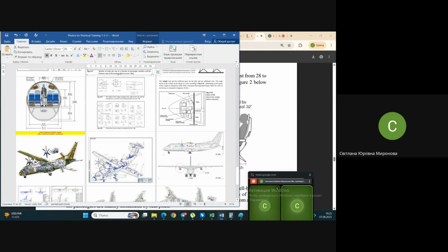Approximately, let's agree, up to Mach 0.6, it's turboprop maybe. 0.6 to 0.8, it's turbofan, maybe of different bypass ratio. And what is higher than 0.8, it's already a pure turbojet. If we agree at least to these values, you need to understand what kind of engine you are searching for.